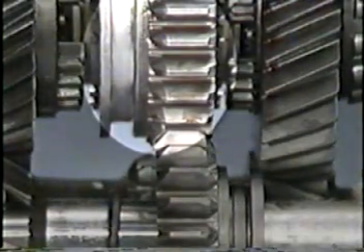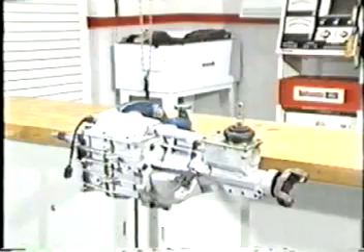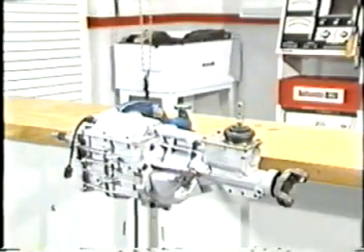One unique feature of the T50D is that the spur gear on the output shaft is actually part of the synchronizer sleeve. Since there's no synchronizer to prevent gear clash, any rotation of the input or output shafts during a reverse shift will cause a grinding noise. Therefore, for this and other transmissions without reverse gear synchronization, gear clash in reverse is usually a sign of a clutch disengagement problem, or not coming to a complete stop before shifting into reverse.